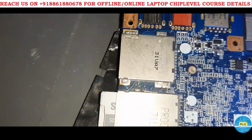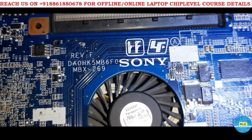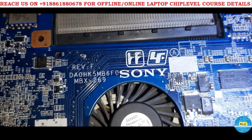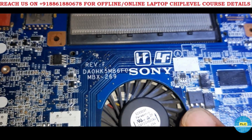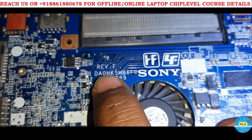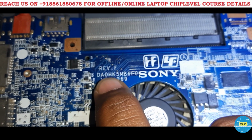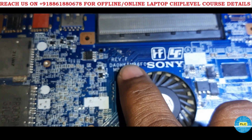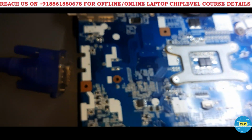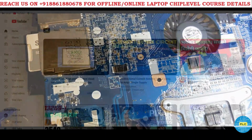Where is it? Yeah, here it is. The complete model number is revision F, DA0HK5MB6F0, MBX 269. See, in this Quanta DA0, we have to leave it. Only 3 digits after this 0, HK5 is there, no? That we have to count, especially in the Quanta series. Okay, now I will explain through the schematic, then you will come to know.